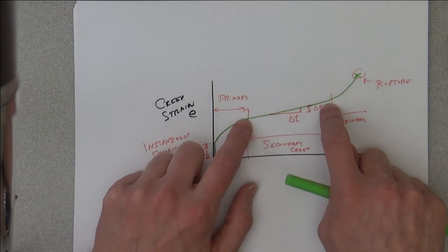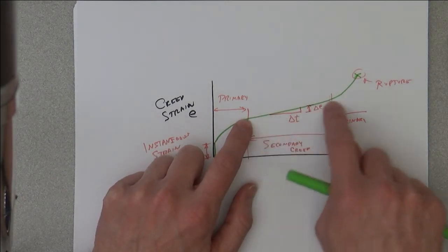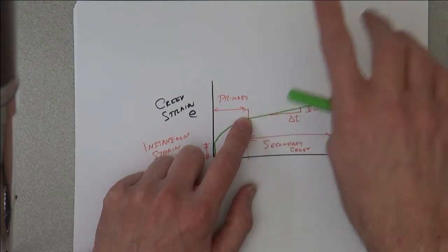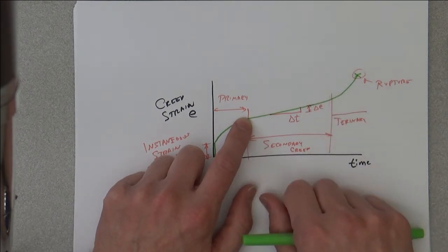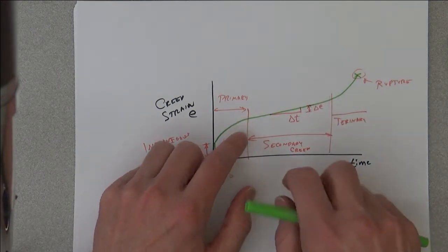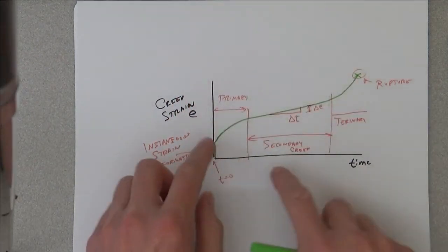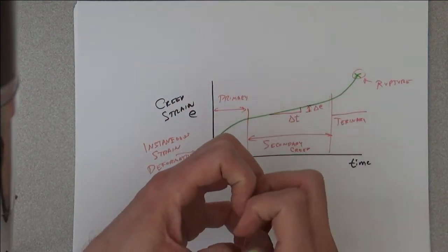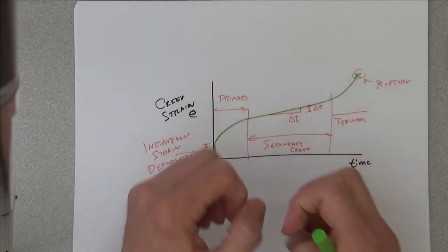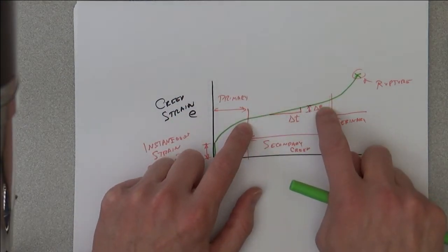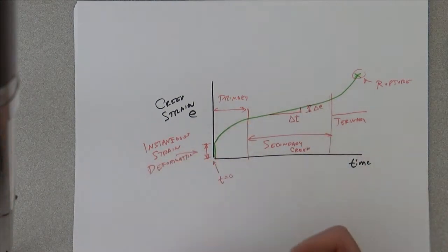In this middle region, we have most of the lifetime of the part, in which we have this kind of slow diffusion of vacancies. You might also have some type of grain boundary sliding, in which these grains in this region start getting themselves aligned, and then in this region, the grains are able to slide past each other very slowly, and again, the grain boundary sliding is assisted by defects.